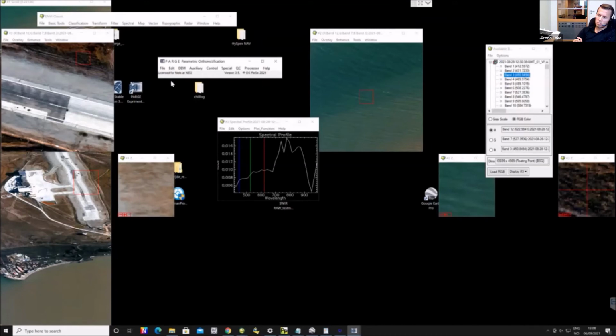Typically, as I mentioned, height reference using ellipsoid instead of geoid, or different geoids, is a very normal error. Another normal error is to use different datums on the elevation model and on the hyperspectral data. You can also have a lever arm, which Agnar mentioned yesterday.